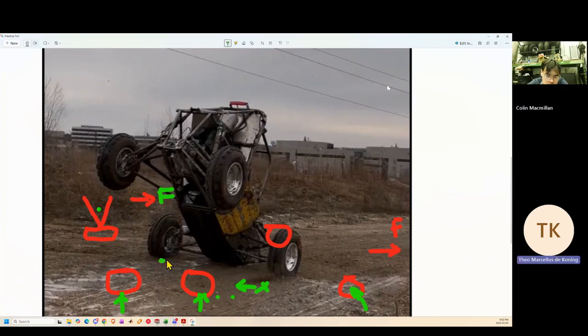In scenario 1, our contact patch we're assuming to be right in the middle here. But in scenario 2, our contact patch is now going to be up here, which will try and rotate the whole control arm this way. It'll put a huge moment this way,